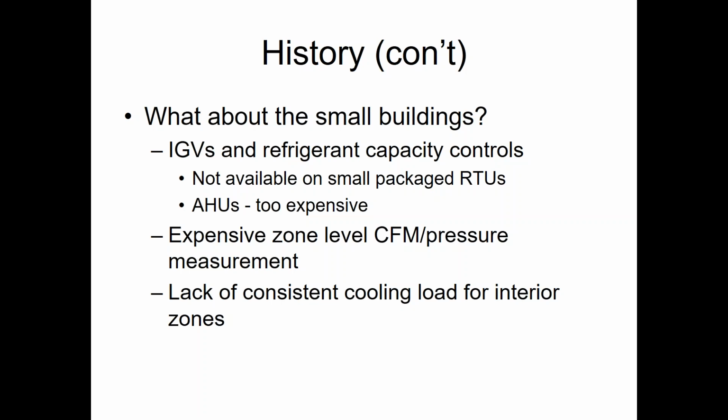But the solutions that we have for those smaller units, typically rooftop units, 5, 10, 15, 20, 25 ton type equipment, meant that I didn't have a VFD. Well, back then I didn't have any VFDs, but I didn't have guide vanes available to me on small tonnage rooftop units, and putting an air handler in would have been totally breaking the budget on some of these little tiny office buildings. So what am I supposed to do?